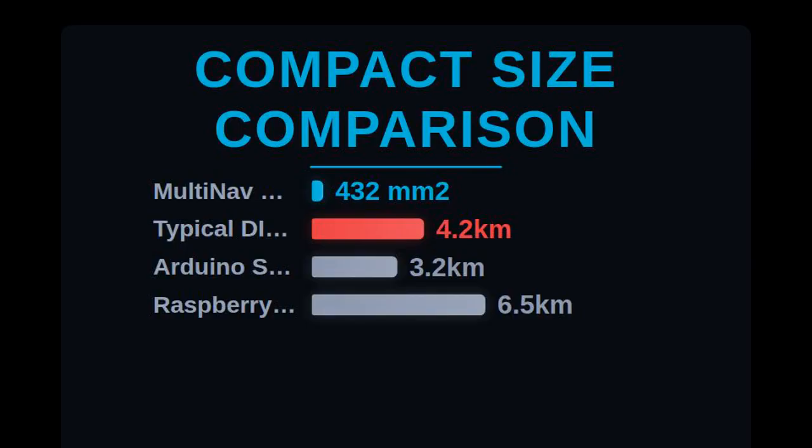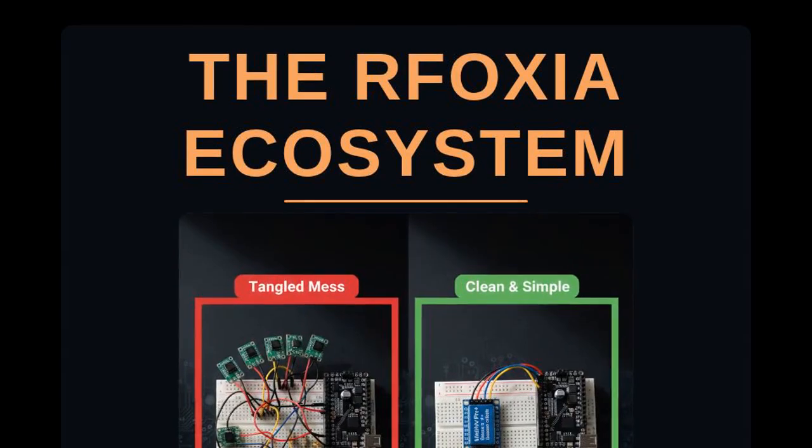Every single one of these chips has a unique I2C address, 0 conflicts. The pull-up resistors are sized and placed, the decoupling capacitors are there, the PCB traces are routed for minimum noise, the power rails are filtered, the board is FCC certified. You connect SDA, SCL, power, and ground, and you start reading data.